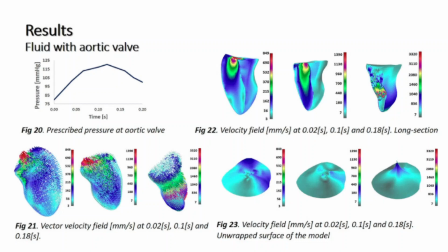For unwrapping of the surface, we use least squares conformal maps. This method is implemented in the libIGL library. In computer graphics, we denote a surface parameterization as a map from the surface to two-dimensional space. It is usually encoded by a new set of 2D coordinates for each vertex of the mesh. Least squares conformal maps minimize the conformal or angular distortion of the parameterization.